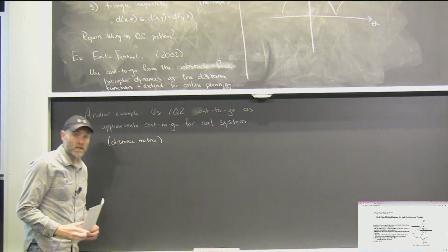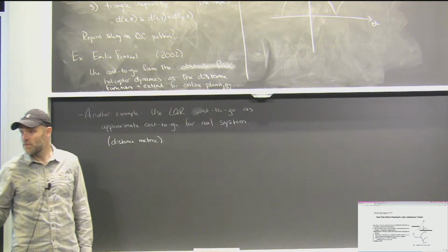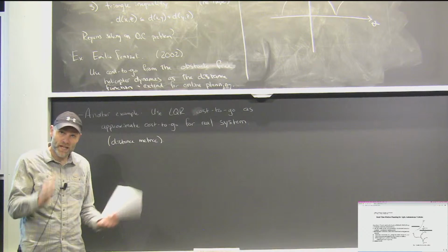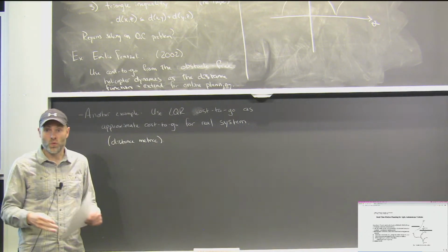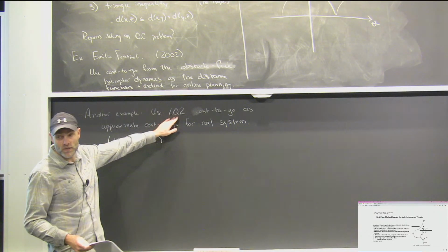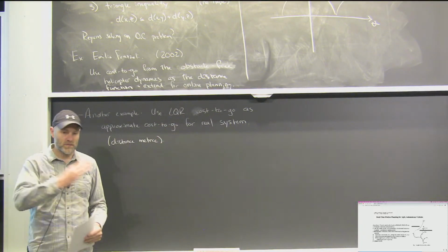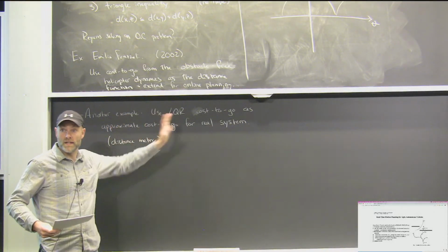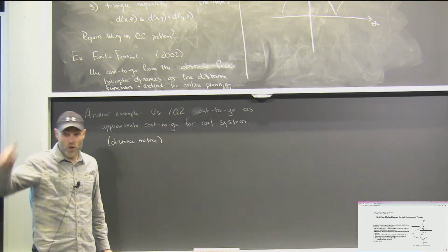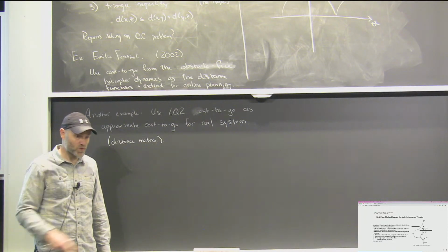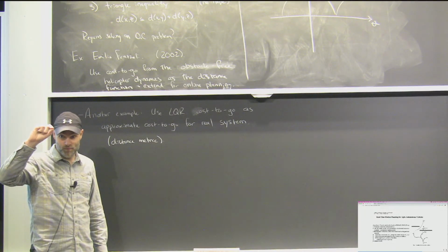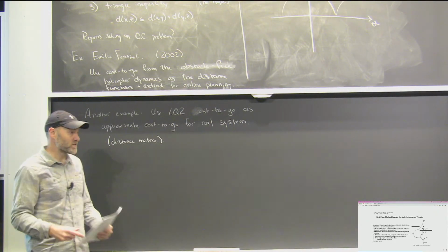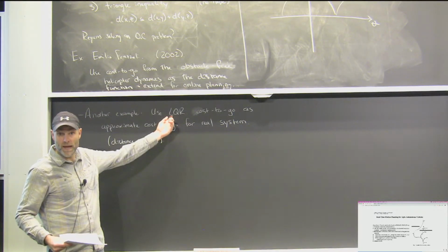There's a few variants on that that could work. Now, the minimum time problem and the LQR cost problem are not the same. So if you want to do a minimum time LQR, then you have to do a little more. It's not just solving a Riccati equation. It's solving a small time varying Riccati equation. It's a little bit more effort, but you can make that work. At least the notions of phase portraits and velocities, the fact that things move around in a circle in phase space, LQR linearizations can capture that.